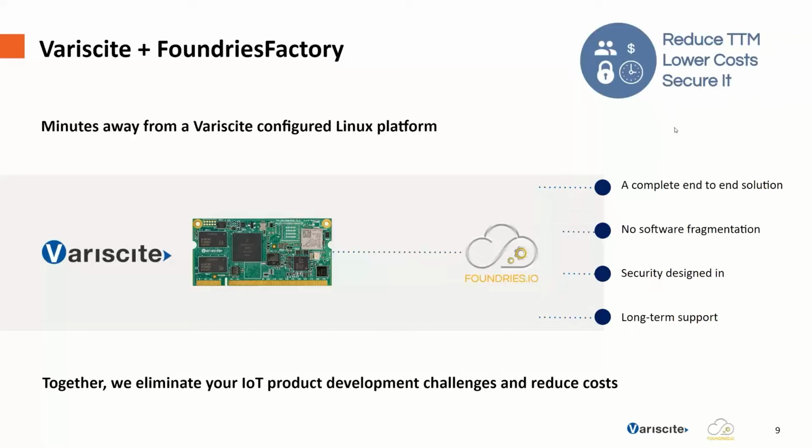The other part is we have security designed in. Now, people say security, what does that mean? We have root of trust provisioning. So from the boot ROM forward, we have a root of trust established that can either be done with the SoC features that are there with the replay protected memory block, which we'll talk about in a moment, or if you have a discrete hardware security element, we also have integrations for that. So it's turnkey. You don't have to think about how to implement that yourself. We've already done that. It's in the open, so you can see it and you can audit what we're doing, and basically you can turn it on as you're starting to go into manufacturing. So you can start your development now and not have to worry about that and turn it on later.